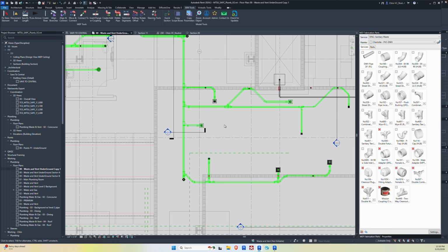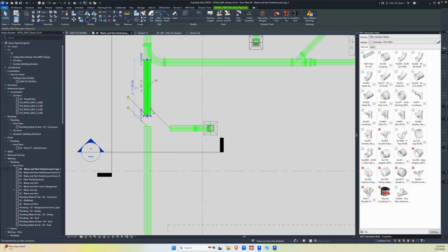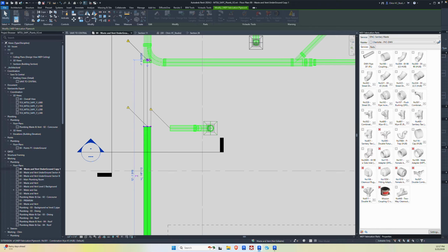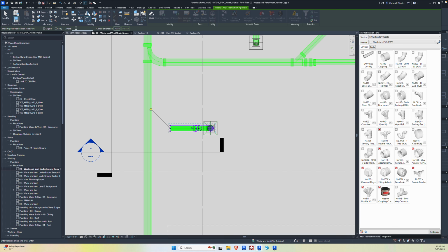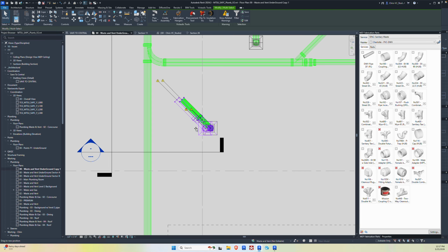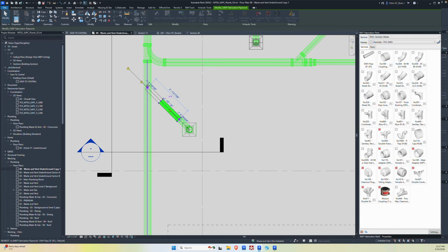and still be able to work it quickly, align branches, move things around, even if the pipe was at an angle. So let's drag this back here. We'll delete this. Delete this. We'll drag this over here. Even if this pipe was at an angle and I rotate it 45 degrees, I'm going to have to push this over a little bit. I can still come in here. I can use the align branch on the fabrication parts. You can see something disconnected there. But I can still go in here and I can connect it.